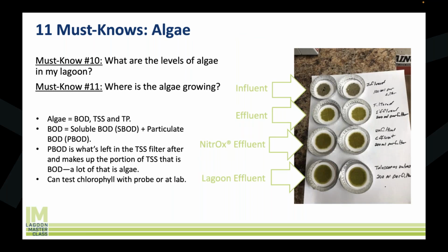And you'll see this, if you did this every week throughout the year, you'll see the chlorophyll levels in the wintertime be low because of course algae doesn't really like to grow when it's cold as much. And you'll see it pick up and spike in like July and August when it's hottest and when it's had a lot of chance to grow. And you'll see this precipitous rise, right, if you do it on a regular basis. And that can help you to understand how much algae is growing, if you need to go out there and manage the algae in order to avoid it.